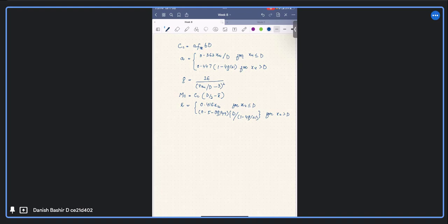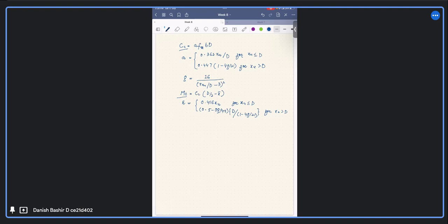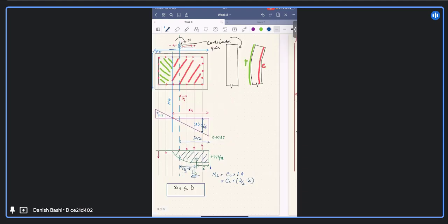Now, this is the compressive force carried by the concrete. This is the moment resisted by the concrete. So next will be the rebars. What is the amount of compressive force carried by the rebars? So CS, the resultant compressive force in the steel, will be the summation, I running from 1 to n, of (FSI minus FCI) times ASI. I will tell you about all these terms.